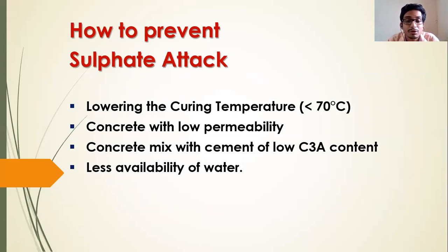So, C3A content: the content of C3A in the cement should be low, because the C3A in the cement reacts with the sulfate to form ettringite-like structures, and if the moisture availability is high, then the structure may also suffer from that sulfate attack.